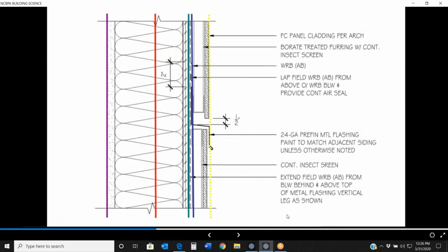What typically happens, though, is something due to schedule or cost or materials available or construction type. What we usually end up with is batt insulated cavity walls. If we can get a rain screen on the outside, it's fantastic. We're going to have that everywhere we can. I highly recommend it. But we're still able to get our control layers.